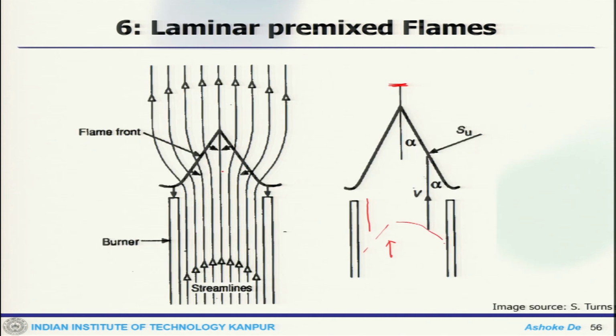So, the flame can only be stabilized on the burner for certain flow velocity limits. That means, it will be attached to this burner for certain conditions. If I inject with too high a velocity, the flame would be pushed back. So, for a defined or controlled limit, this flame would only be stabilized at the burner, otherwise either it would be pushed back or it may lift up.